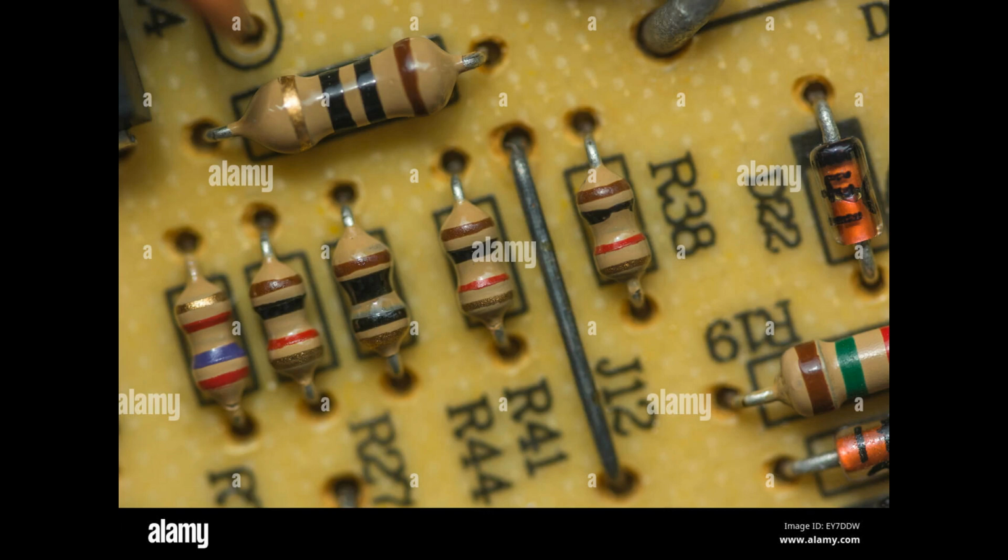of watts. Heat sinking: in high power applications, such as power amplifiers or power supplies, where resistors may need to dissipate a significant amount of heat, heat sinking techniques, like attaching the resistor to a heatsink, may be employed to enhance heat dissipation. Temperature coefficient: the temperature coefficient of a resistor also affects its power rating. Some resistors are designed to have stable resistance values over a wide temperature range, while others may exhibit variations in resistance as they heat up.